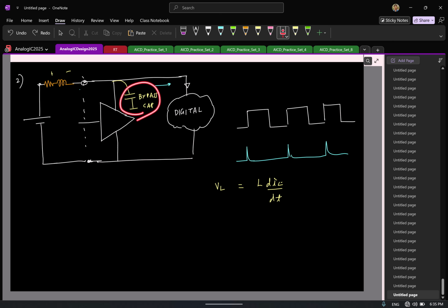Again, remember, capacitor is like a voltage source. Infinitely large capacitor is an ideal voltage source. So in principle, if you want to mitigate this, you want to have an infinitely large capacitor, but of course, you can't do it. So you do put a capacitor and reduce it, but it's still not going to be fixed. So the supply you see for your circuits will fluctuate like this. So I'll say that the supply is going to have supply noise.